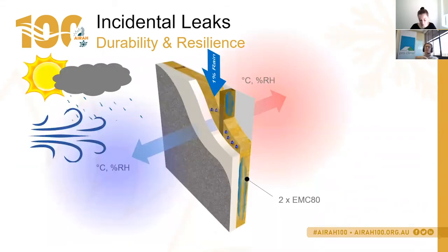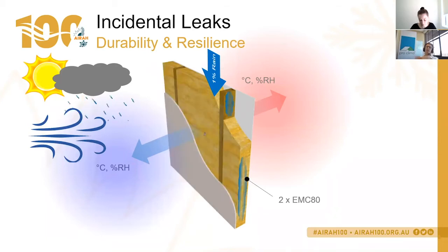Next. So what that is essentially, when you've got a system and you're looking at how these systems operate, you use the external weather conditions, dump 1% driving rain behind a face sealed system, and then see what happens to the criteria around mold growth and corrosion. That also is effective if it was just a face sealed fiber cement sort of system. But what becomes critical in those sort of systems is when you've got render coats on the outside and if that moisture can dry back out. So the coating systems are critically important as well.